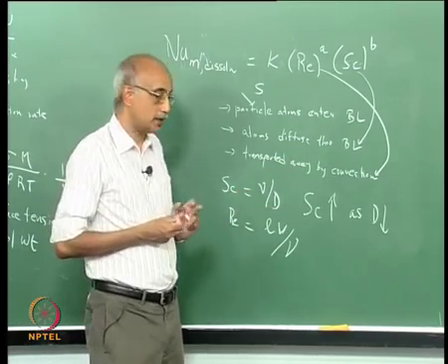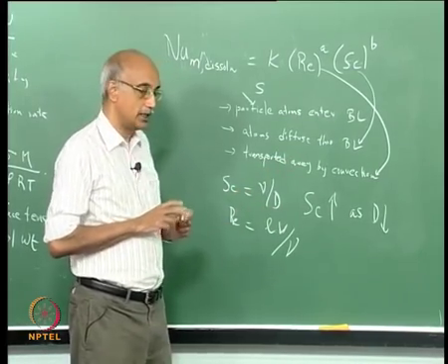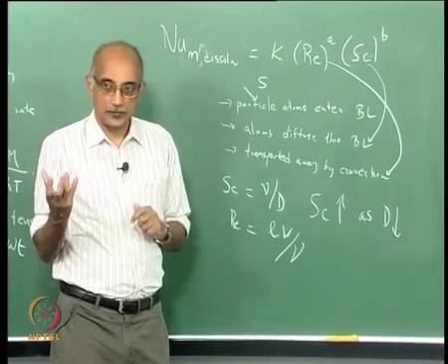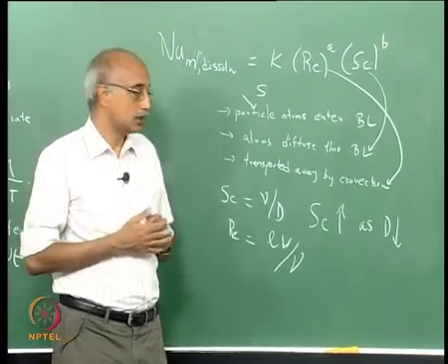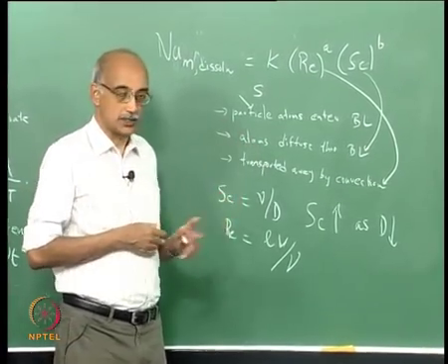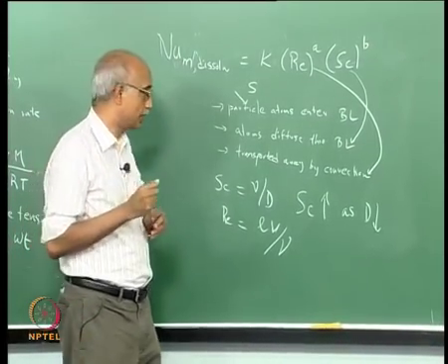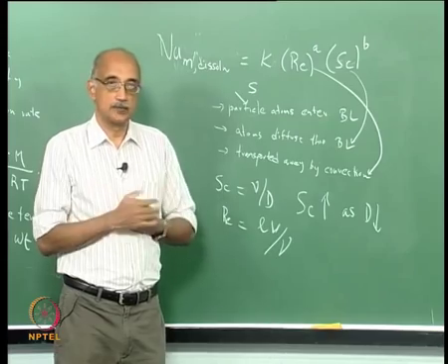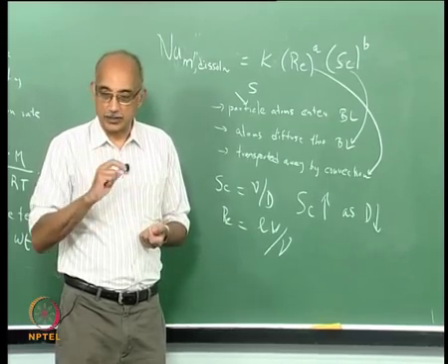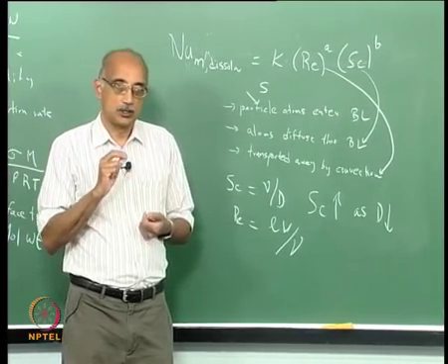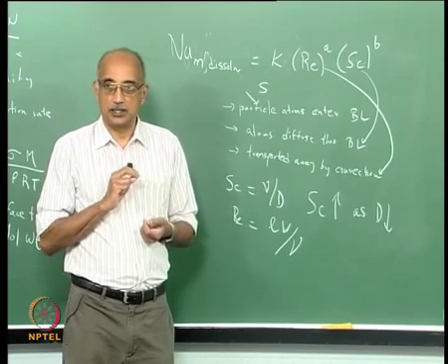In the case where you have essentially a quiescent liquid in which the particle is dissolving, the diffusion process becomes the critical process. In order to get a high rate of dissolution, you have to maximize the rate at which diffusion happens in the liquid.